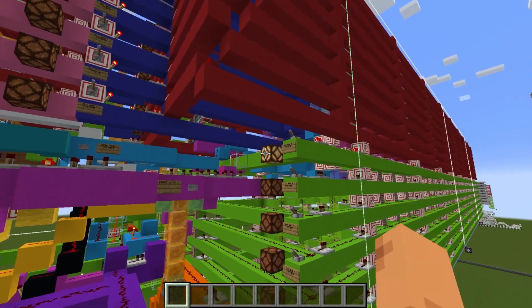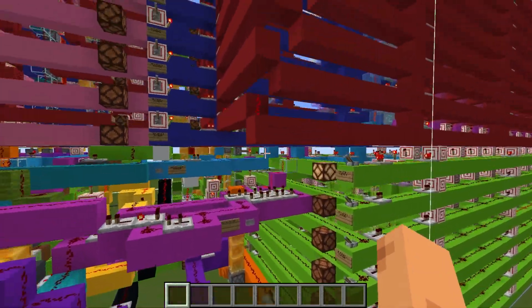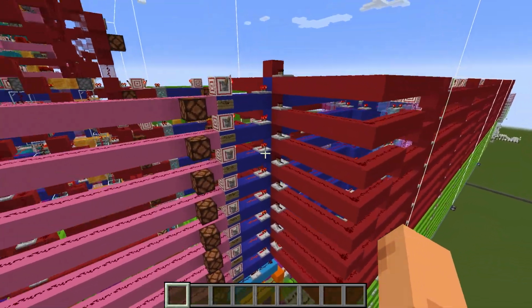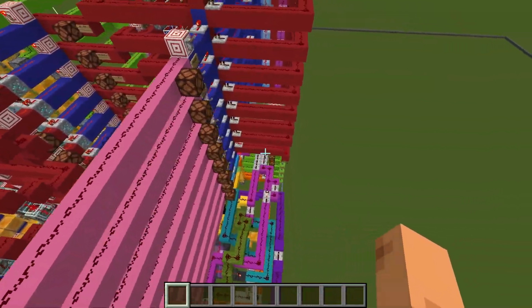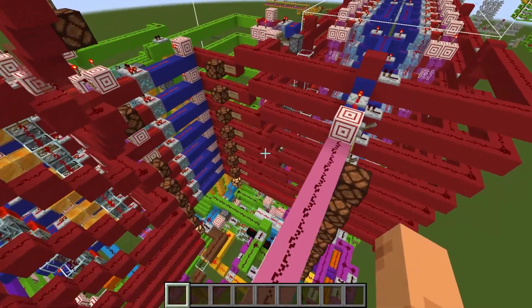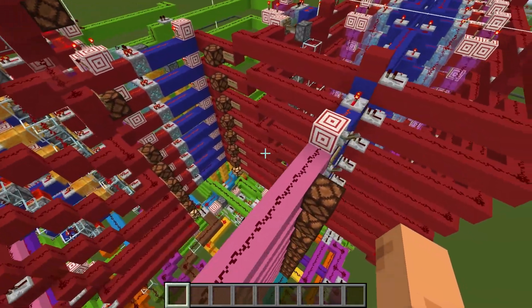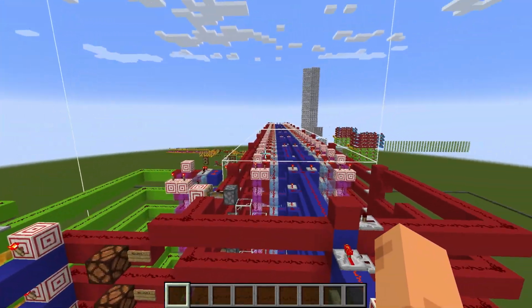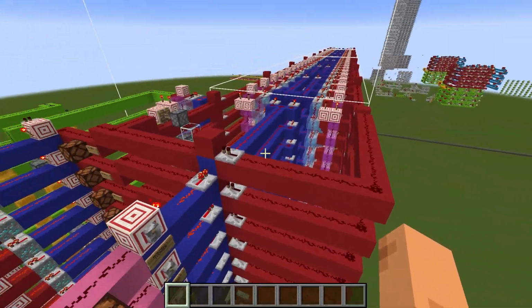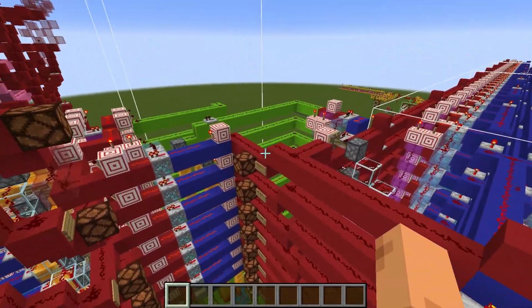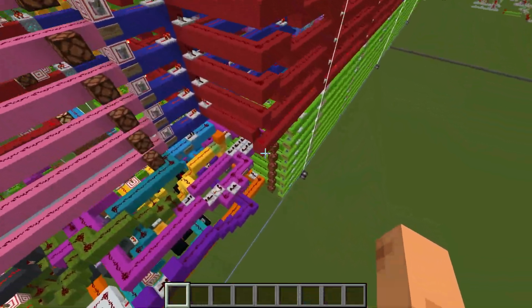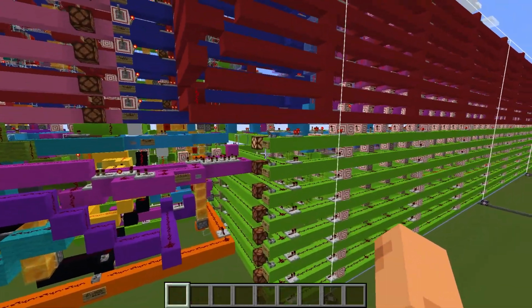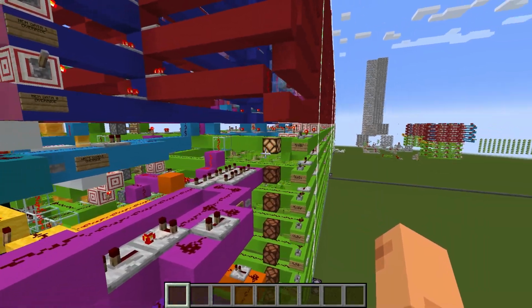So it's showing the odd address, but it's basically ready to read from address 0 and 1. That's just an artifact of how the dual read input is designed. Remember, I said that it would read the even byte and the odd byte at the same time, and then use the even one for the opcode. So it's showing address 1, but you can interpret that as 0 and 1.